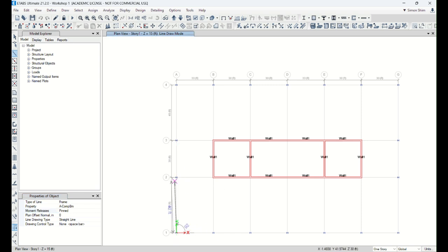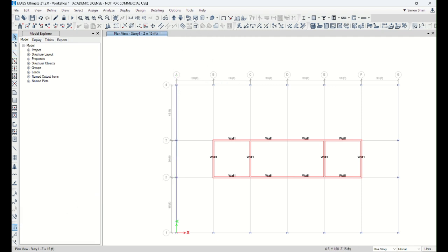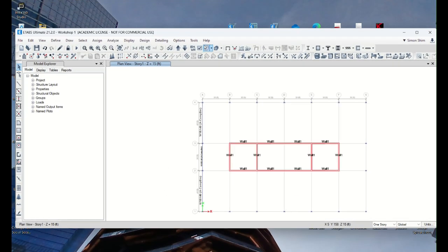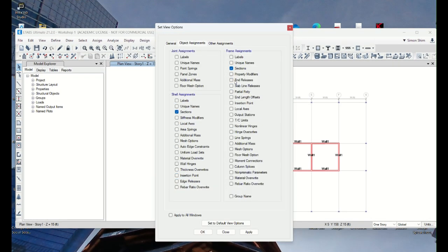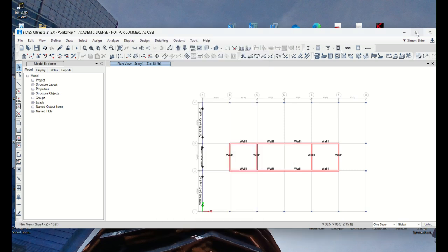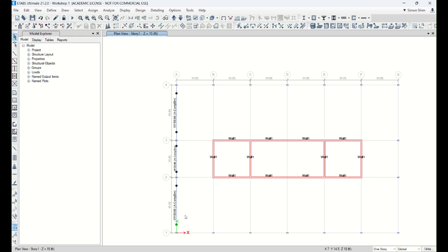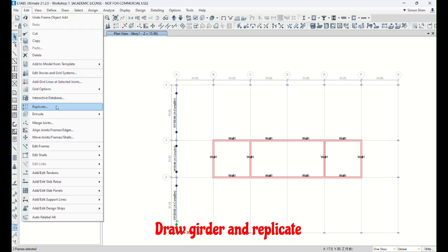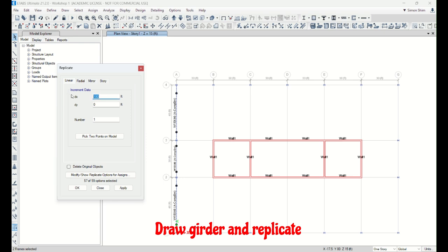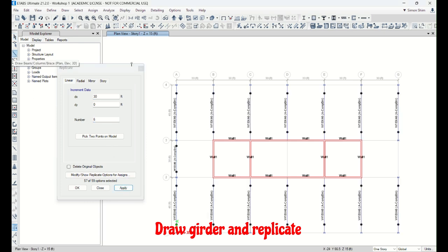So this graphic is a little sensitive. I'm gonna draw the beam like that. Since we picked the pin, in this checkbox I'm gonna turn on the end moment release. So you see that the beam has a simply supported connection, right? So you could just draw the same by clicking, or I'm gonna just copy, replicate, same thing, 30 feet, 1, 2, 3, 4, 5, 6, 6 times, right? I can copy this.